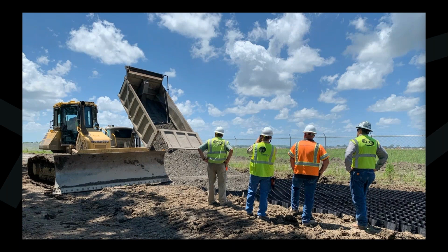And something to point out, geocells and geogrids start with the same concept of how they function, but geogrid performance is directly related to a high friction angle of the infill material. It's why they need that high quality engineered stone. So basically, the higher that friction angle, the better the performance a geogrid is going to have. And that really contrasts with geocells and how the GeoWeb system functions by being able to utilize that low quality aggregate, and it still performs just as well, still has that strength capacity.